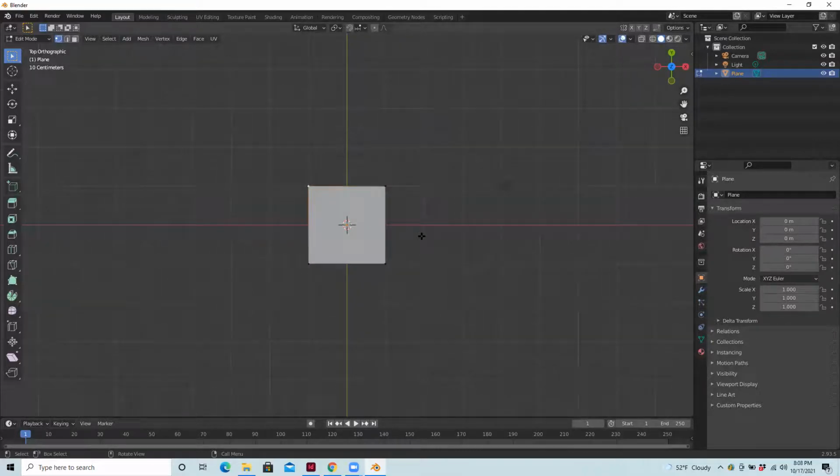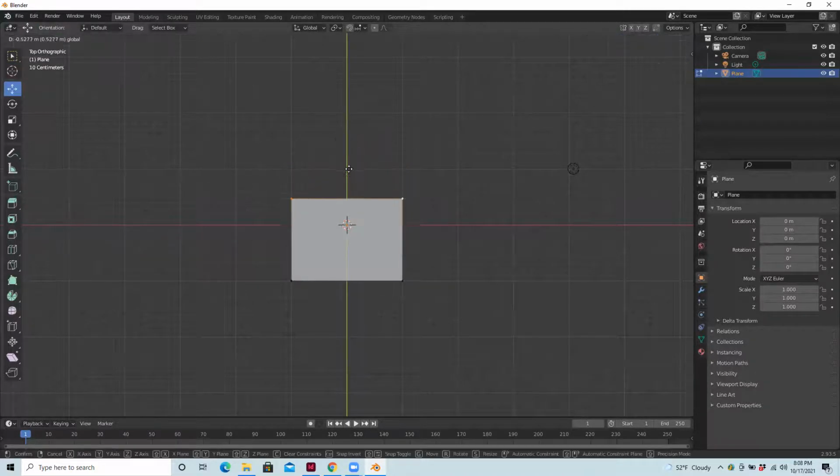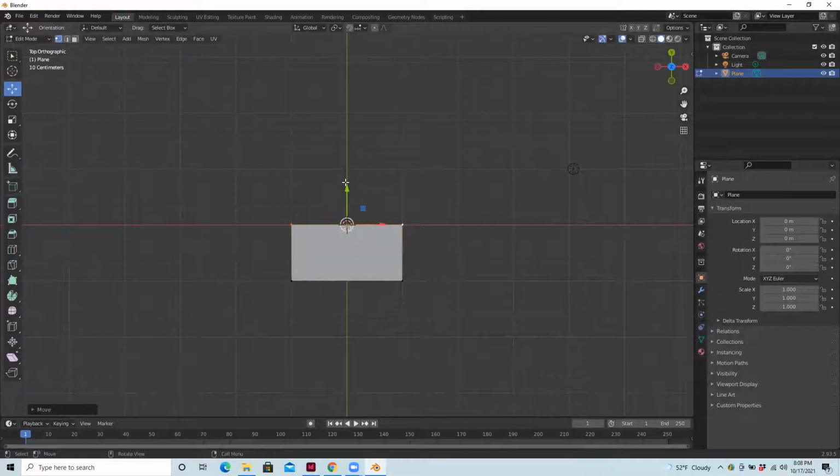I forget I can zoom in closer, by the way. I think I'm going to just roll the mouse wheel to get a little closer. And then I can use Shift and I'm going to select the second vertex in the upper right corner. And then I'm going to switch over to Move Tool. And I'm going to drag down. Just going to want to make this look more rectangular in proportion. Maybe I'll make it about half the width that it used to be. And I was pulling on my green arrow just to move it in a single direction along the y-axis.